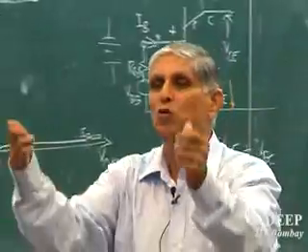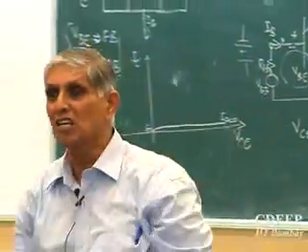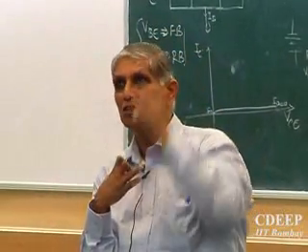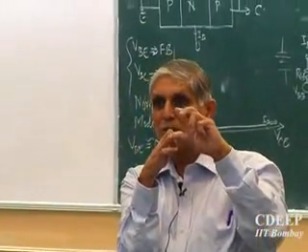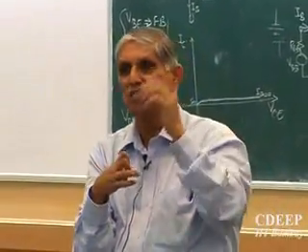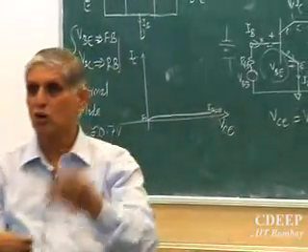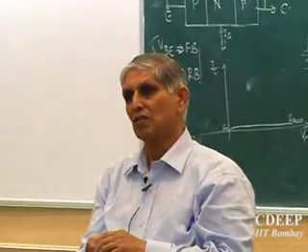So far we said change the voltage of the device, so what currents do I get. Now I am externally seeing a result, because that's what the circuit I will see. And I see, oh, VC is dropping. So I say VC dropping must be VB plus VBC dropping, otherwise why should VC decrease? This occurs because that IC times RC drop keeps on increasing as the base current starts rising.